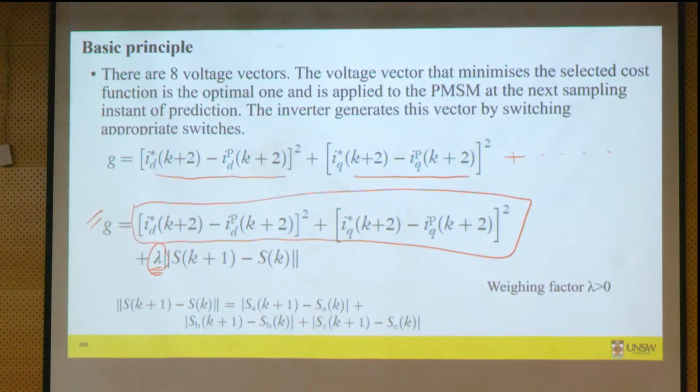And this is actually important, to have switching loss minimization, because when we are using prediction, your space vectors could be anywhere in that space, in that hexagonal plane, right? So if it is anywhere, you may be turning on and off some switches unnecessarily. So switching loss is always higher in this type of cost function based control, and that's why switching loss minimization becomes part of your cost function.